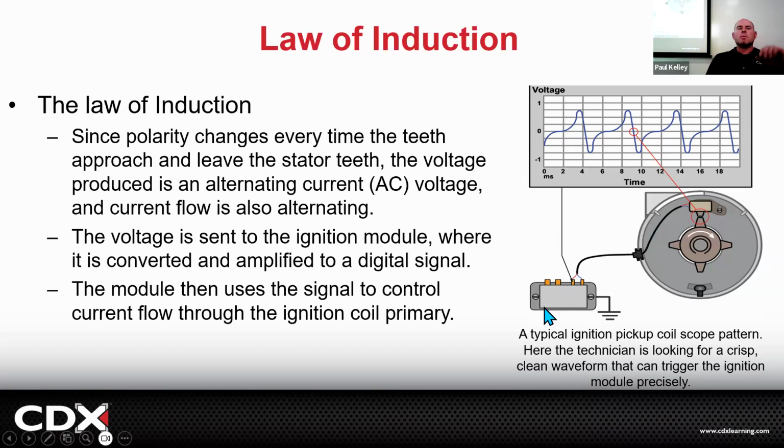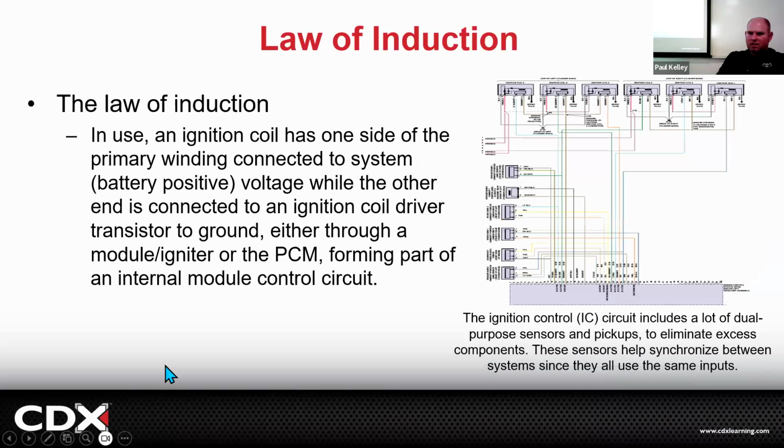That means it's time to fire the spark plug. So this ignition module will actually be charging the coil and then take the ground away from the coil, and that will induce the primary to the secondary, and that'll make the chispa, right? The chispa, the little spark. Okay, but if it's a big coil, that'll make the rayo, the lightning. Okay, cool. So that's the idea.